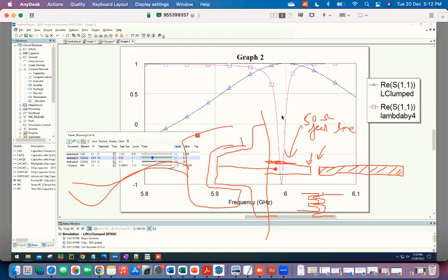When you design, you want the Q to be very, very stable, so you design it on chip, or with the lumped element capacitor, you require to do that. But usually, these kind of capacitors are almost always made as a gap or an interdigitated kind of capacitor.